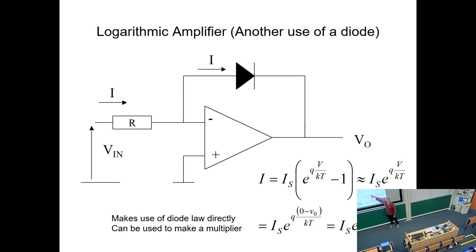And these are constants-ish. Charge of electron, Boltzmann's constant, and absolute temperature, or temperature in kelvins. Obviously temperature may not be constant, but we'll assume it is. And then there's a -1 to give us what happens in the reverse direction. So IS becomes that. Reverse saturation current becomes -IS. So as we only ever use diodes in the forward direction in this kind of circuit here, we can forget this -1, and we end up with this. So we've got an exponential relating the voltage to the current.